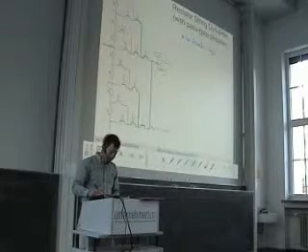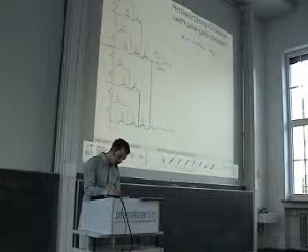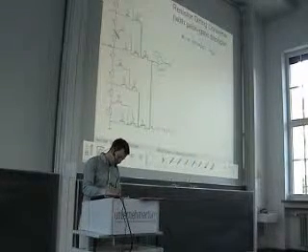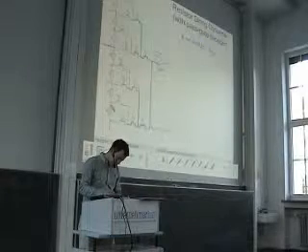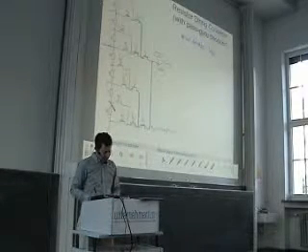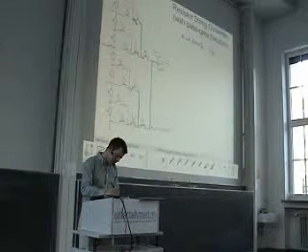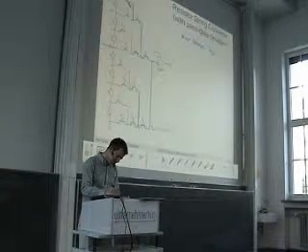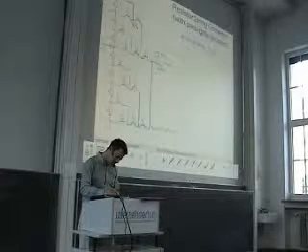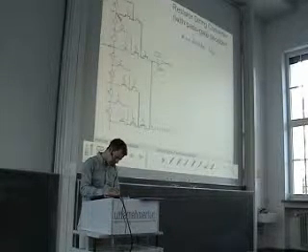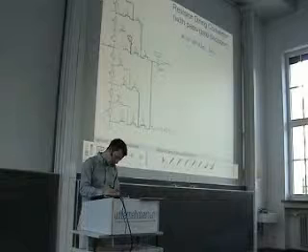And then of course we can continue like this and take the next bit, subdividing the previously selected subrange as well. So we can use now, in this case of a 3-bit DAC, the LSB in order to select the final voltage.